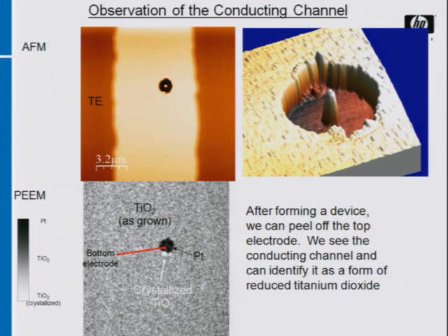And yet people would make measurements, and they saw that the electrical characteristics of the devices did not scale with the area of the device. And the reason was because, in fact, in these older devices, people had to do what was called a forming step. And the forming step literally created a switching center, okay, which is shown here. We expose this literally by ripping the top electrode off the device, and you wind up seeing that there is some sort of interesting pillar.